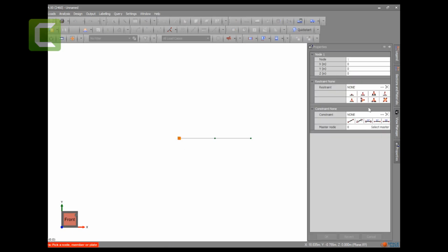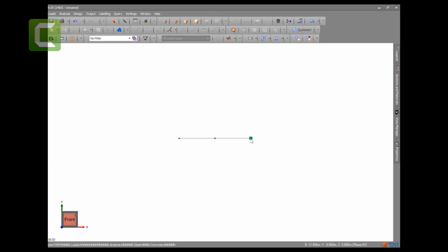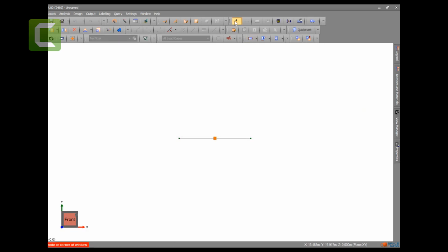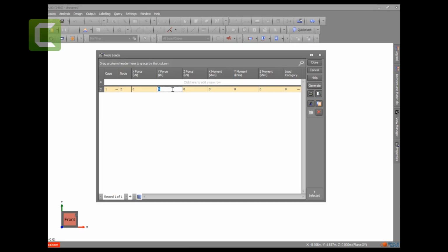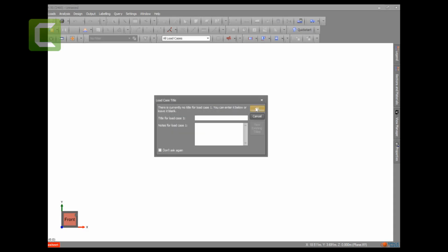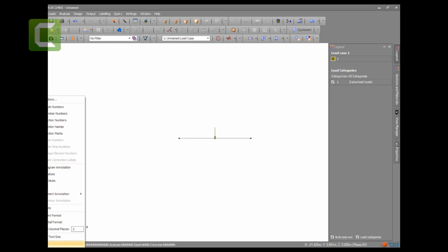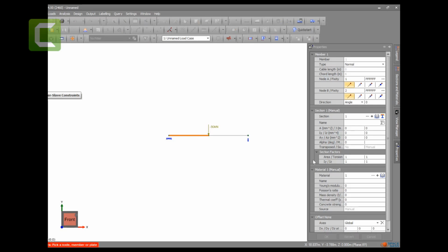Double click on this one. We have these fixed supports and castors. We have a single click or double click, and we have roller supports here. One click, 50 kilonewtons load, minus y, 50 kilonewtons. Hit OK and OK and OK. So if you can't see that one, you can put diagram annotations and hit OK. You can see you can put these fixed beam and rollers.